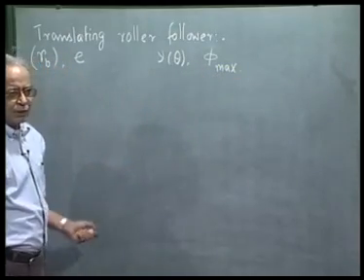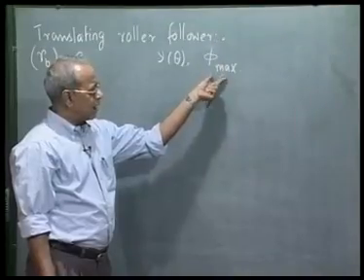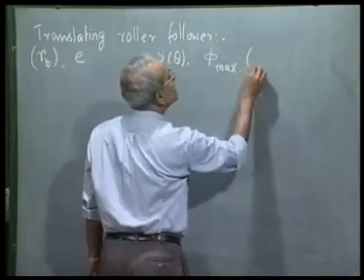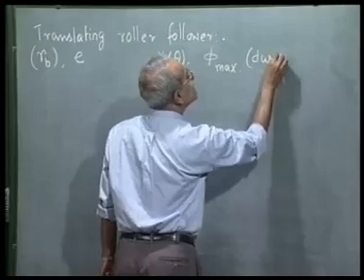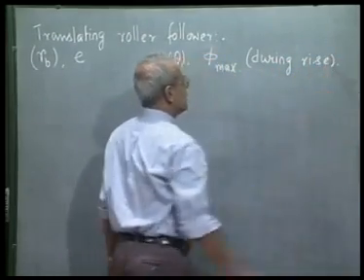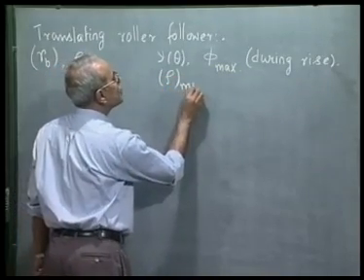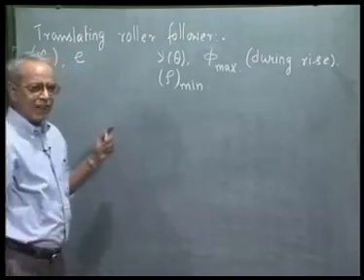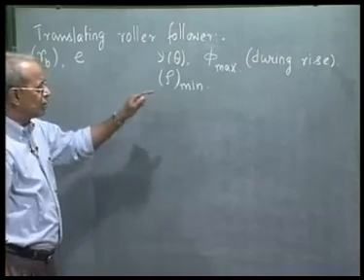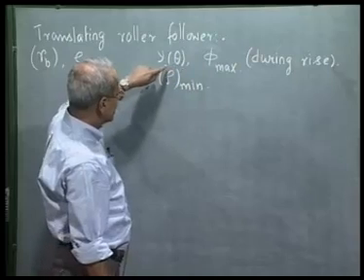As we know, during the rise of the follower, this angle is critical and it should not be allowed to go beyond a prescribed maximum. So phi max, let me say during rise, is also prescribed, and rho min of the cam profile, as I said in case of a flat face follower, is dictated by the contact stress point of view. But what we will do here is satisfy this maximum pressure angle condition for a given y theta.